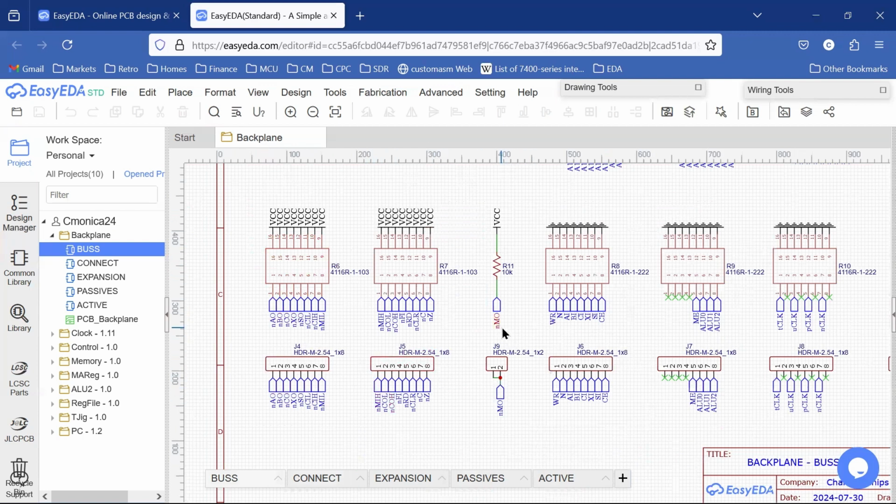This is our not memory out signal. I don't know if we really spoke about this a little bit, but if you remember, I wanted to provide a forward path for direct memory access. So we need a signal that will turn off the memory address register from driving the address bus. So that's what this signal is, and we have also a breakout header for that.